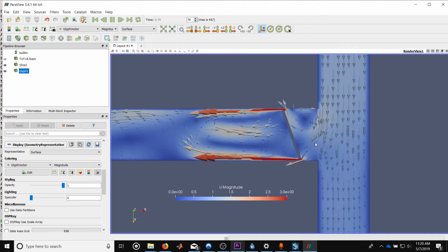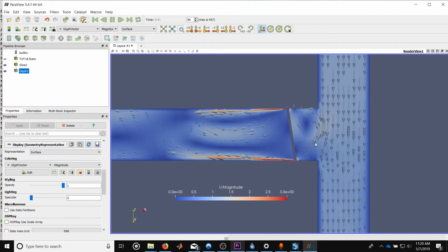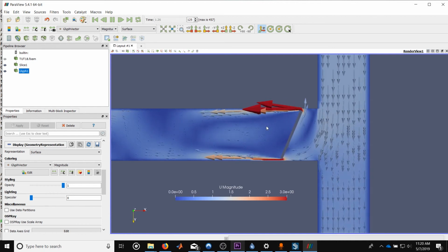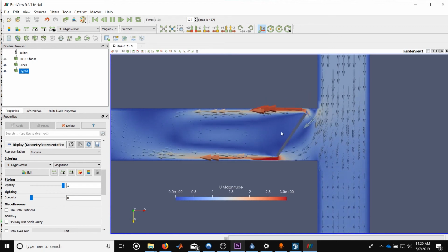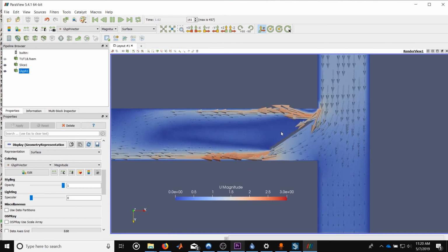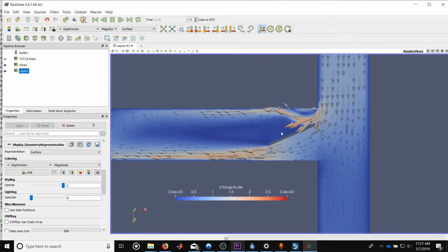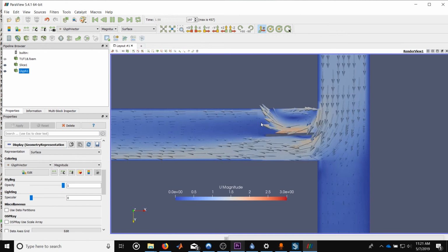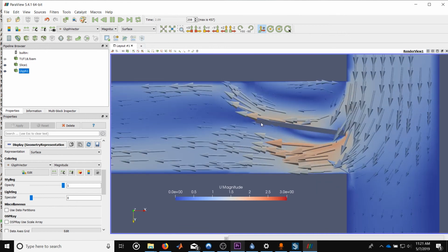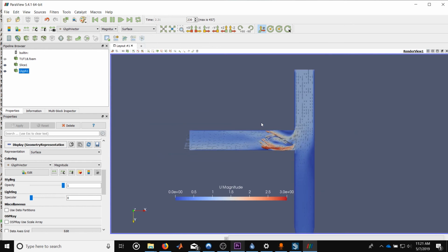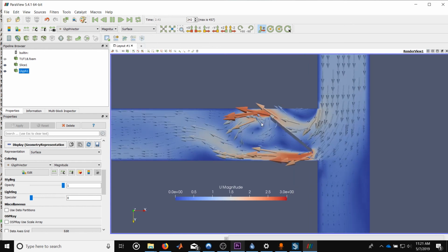The next step in dynamic meshing, which is not at all covered by this video, is how if you had two interlocking dynamic meshes and you couldn't have a solid body rotation, it was necessarily deforming the points. That's much more complicated and will usually require remeshes at every time step. Luckily, we don't cover that. I don't feel that's absolutely necessary, but it is quite difficult. And once you've mastered this, that is the next step.